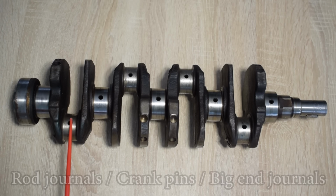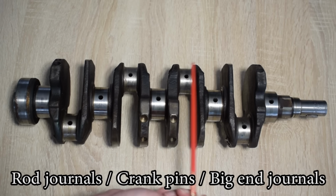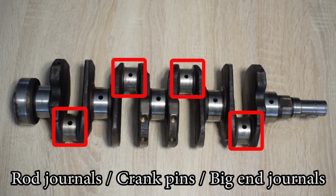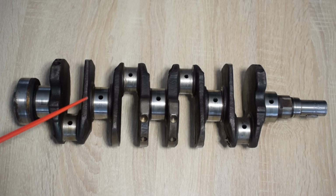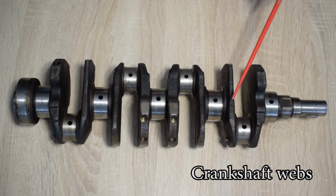These journals, which are usually smaller than the main journals, are called rod journals. They're also known as crank pins or big end journals. They're called big end journals because this is where the big ends of the connecting rods are connected. The rod journals are connected to the main journals via crankshaft webs.